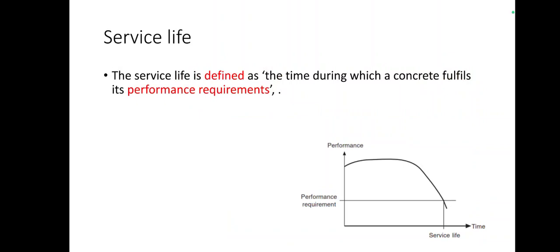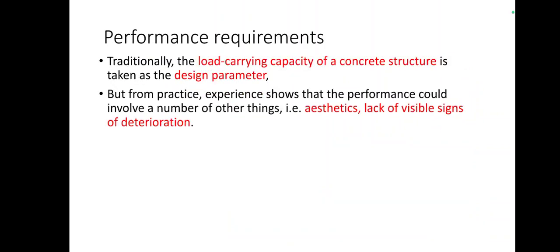And what is meant by service life? Service life means the period in which the concrete is doing its performance in its lifetime. That is called service life. And performance required means, normally from a design point of view, concrete performance is calculated with its load carrying capacity, but actually that is not enough. Not only the load carrying capacity, the signs of distress, deterioration happening, and the aesthetic view are also very important.